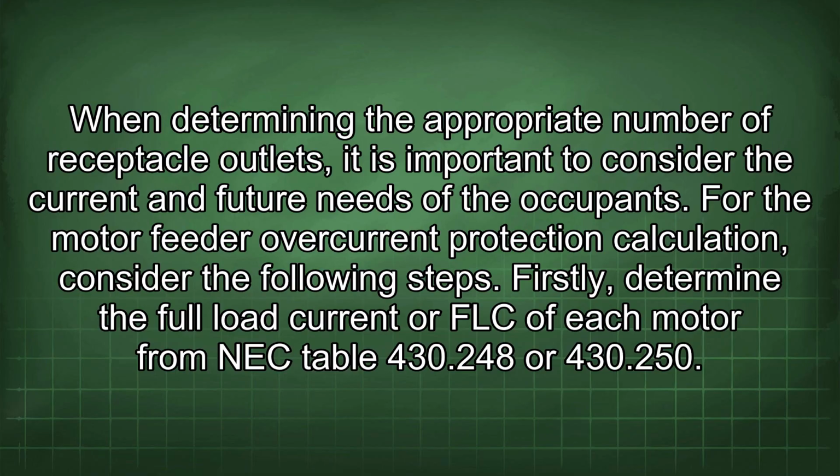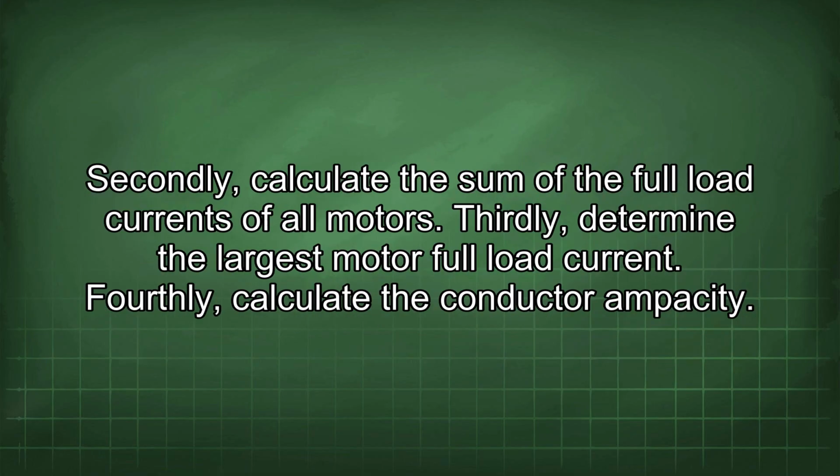Firstly, determine the full load current, or FLC, of each motor from NEC Table 430.248 or 430.250. Secondly, calculate the sum of the full load currents of all motors. Thirdly, determine the largest motor full load current. Fourthly, calculate the conductor ampacity.